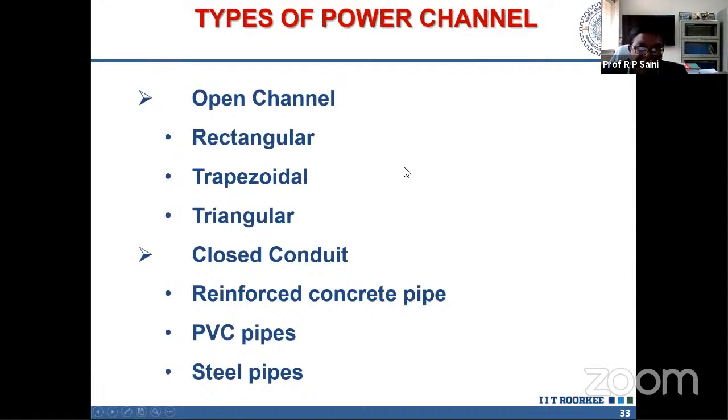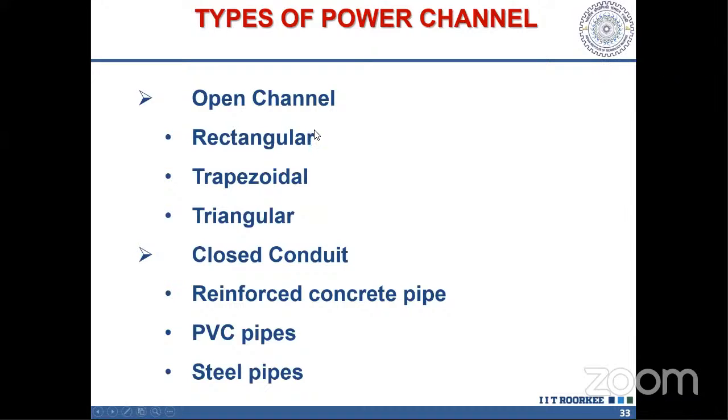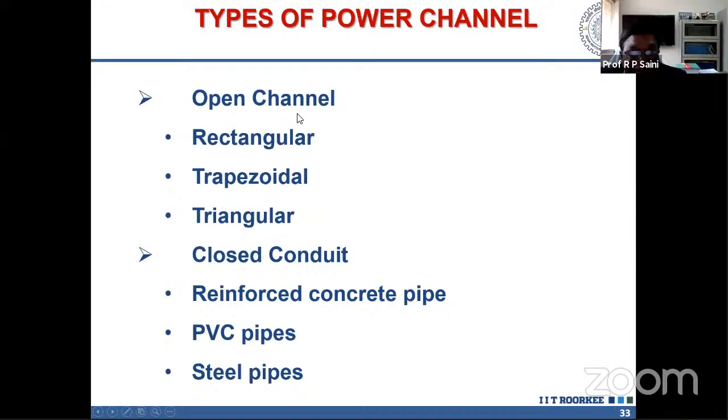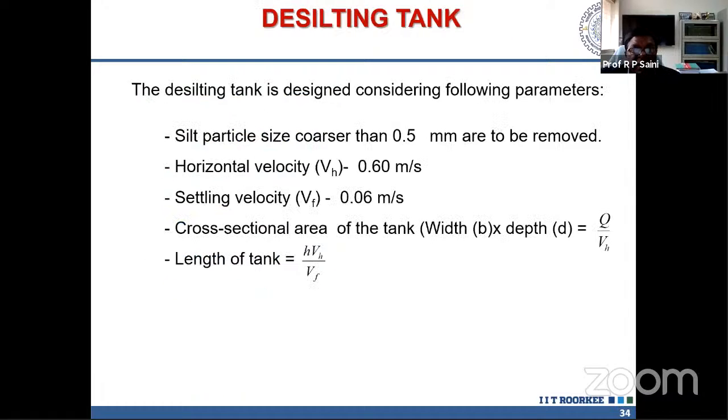Anyway, is this a power channel or what is this? Yes, it shows types of power channel. The power channel transports the water from the intake to the forebay tank. Again, we have various types. It's simple civil engineering that you have to apply to design the power channel, and to design the desilting tank.